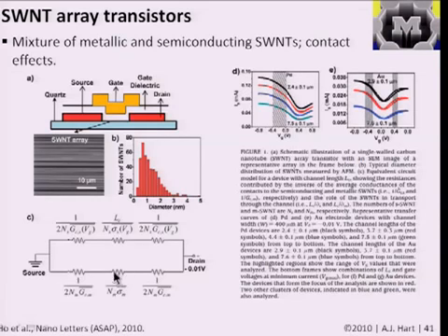And so here the resistor representing the transport through the metallic tubes is proportional to its length, LC, or the channel length here, divided by n sub m, the number of metallic tubes, and the average conductivity of a metallic tube here, sigma sub m with a bar over it. And this suggests that in this case we are in the diffusive regime.